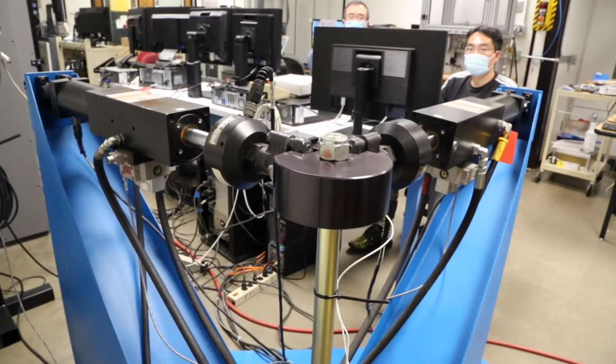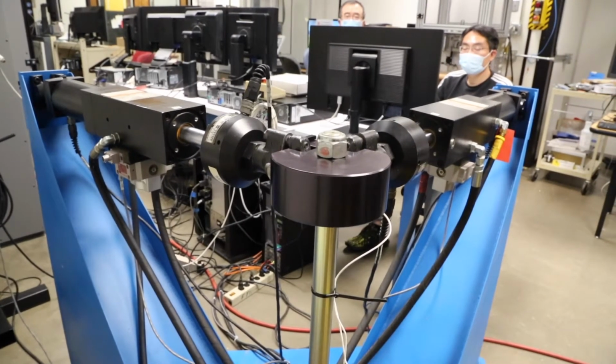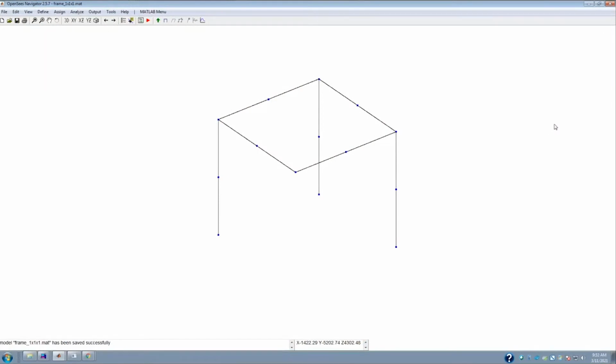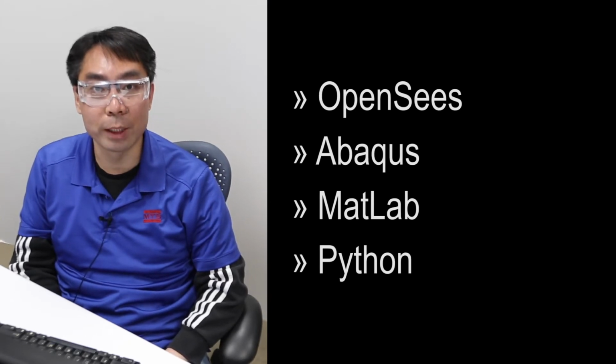It has one column being physically tested. The numerical substructure we are going to run today is this one showing on my screen, which is basically a one-bay, one-story frame structure. And you can see one column is missing because that's going to be physically represented in the lab. We will run several tests today, each time with a different modeling package running the hybrid simulation.